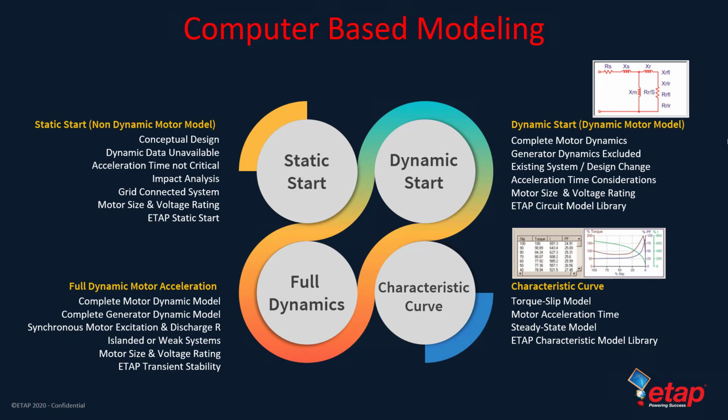Over on the right hand side, we have a more detailed simulation, which is the dynamic starting, and that takes into account information such as the motor dynamic characteristics. It takes into account the load characteristics requirements, however, it does not take into account things like generator excitation and governor systems. For that, we look at the bottom left, which is the full dynamics, and that's using the transient stability engine.